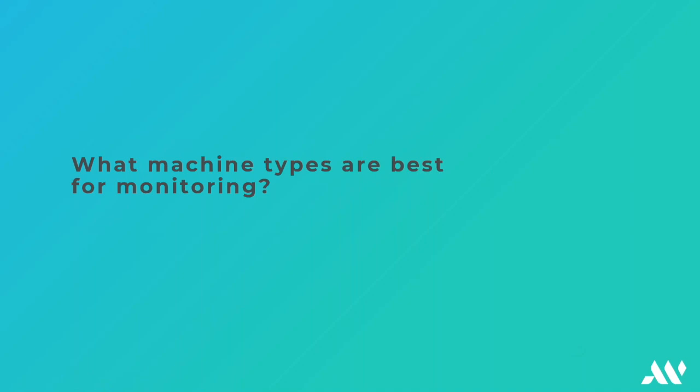Well, I would start with definitely the most critical things you do not have redundancy on. The most critical is where we want to start, and then you work your way down according to budget. But typically, overall, the machines that we're going to monitor are almost every type of stationary rotating machinery.